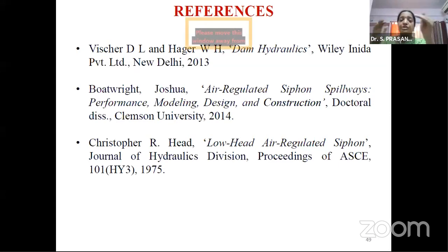Now here I have just used the macro only to look into the depth parameter. For other parameters, as I told you, when you have velocity, which I applied for the other case studies, I have used the macro of velocity. I have used the macro of dynamic pressure, where you can obtain a beautiful graph with different values throughout the profile of the siphon spillway. We have adopted this velocity magnitude macro and dynamic pressure macro.